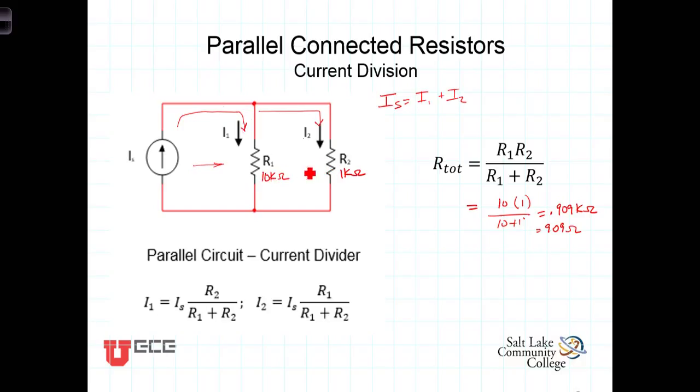If you then open up two paths, even though the resistance here is 10 times as large as this resistance, you'll still have more current flowing through two paths than you would have had through either of those. So more current flowing suggests less resistance, and in fact that's what we see. The parallel combination of two resistors is less than the smallest of the two resistors.